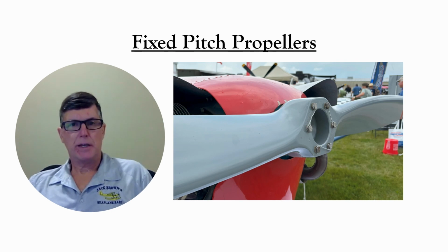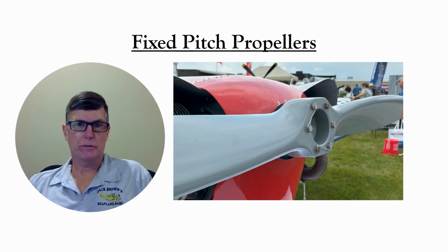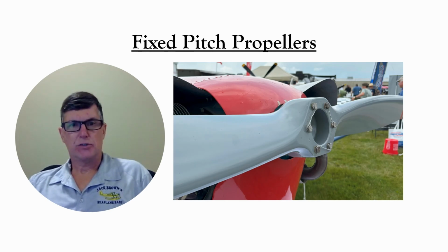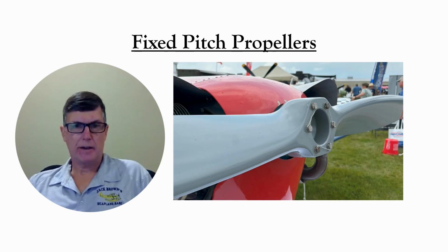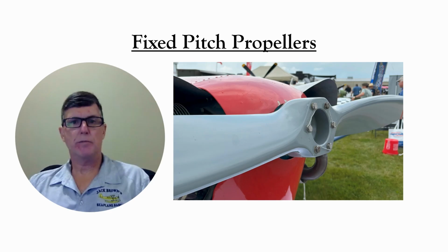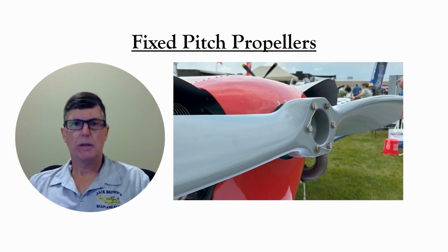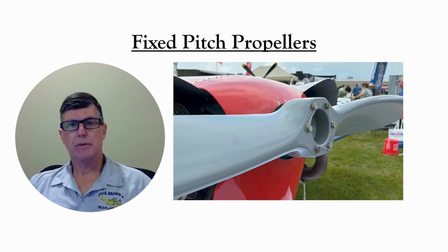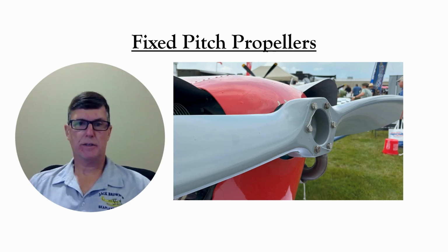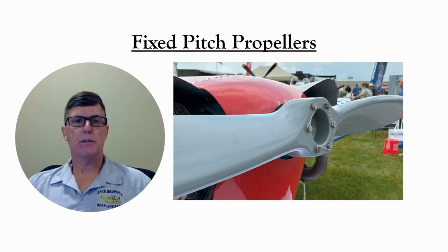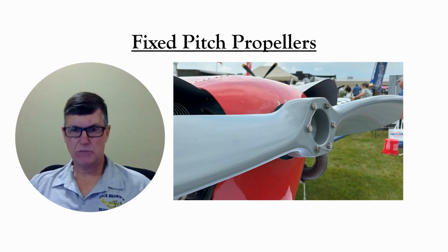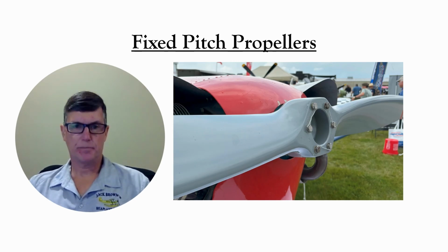The propeller blades are airfoil shaped, like the wings. The blades strike the air with an angle of attack to generate a thrust force, in the same way that a wing produces a lift force. Since the propeller tips follow a larger arc, the inner parts of the blades are twisted so that each part has close to the same angle of attack.